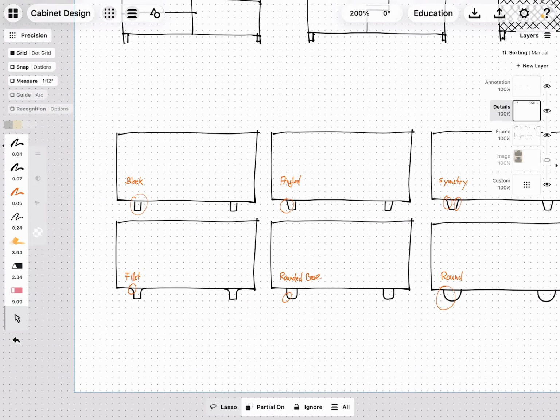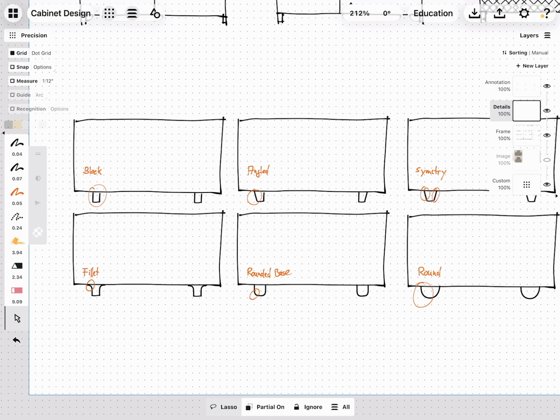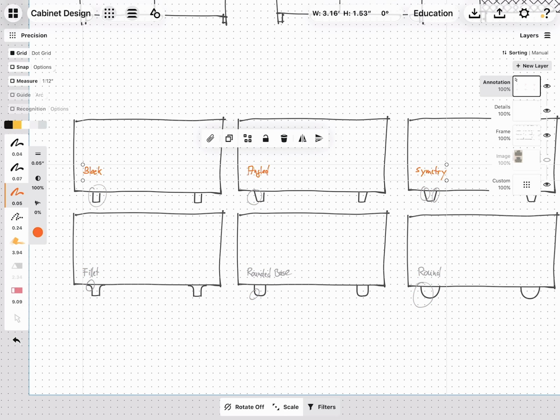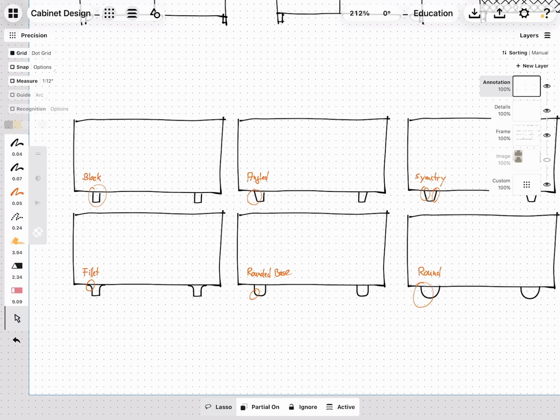The nice thing about adding these annotations is you can do this very quickly. You want to use a little bit of order. You see the handwriting is slightly trying to follow the baseline or the dotted grids. Here, actually, I see they're all a little bit too high. So I will go to active only, select all those and bring them down a little bit once I'm on the right layer. There. So this is similar to what I have at the bottom.